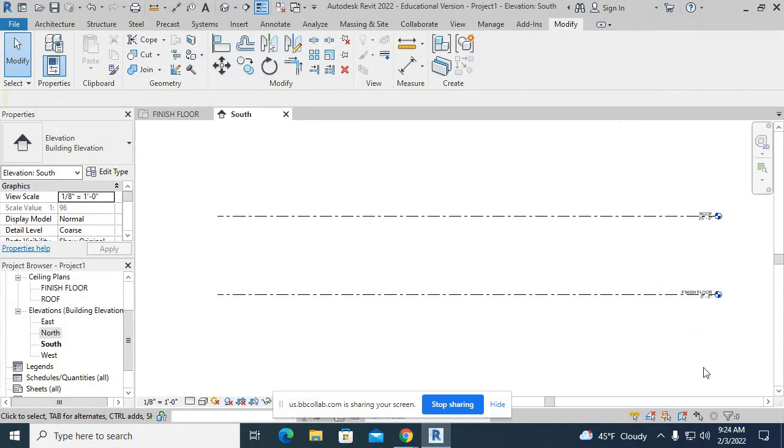It's to view the roof plan. Right now it's looking at 29 feet, and it's trying to show you something above, because originally it was to draw floor plan 2. Later on when we get to roof plan, I'm going to show you how to say no, ignore that and show me everything below from there.